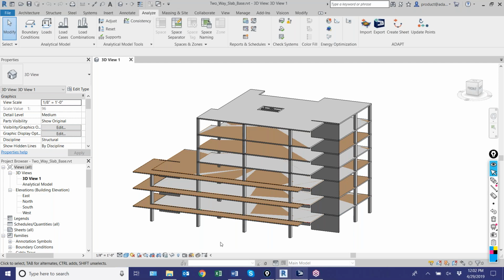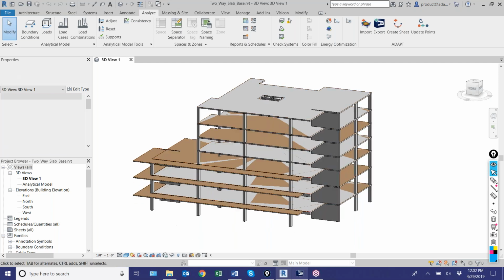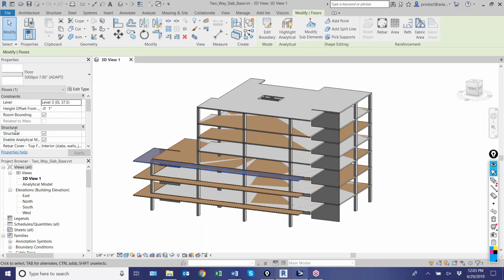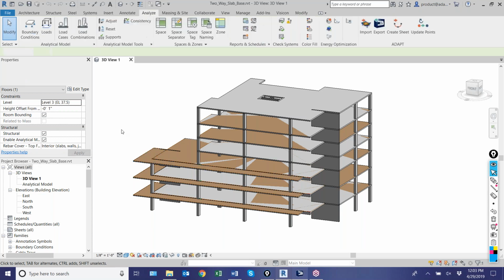Now in the Revit model, an important point is that the Revit model must contain structurally enabled components. So if you select a slab region, for example, this slab region is structurally enabled. You have to have a material assignment as concrete assigned to the component for it to be interpreted by our IMP extract. We access the Revit API, and we're looking for certain things when we extract and write the data.